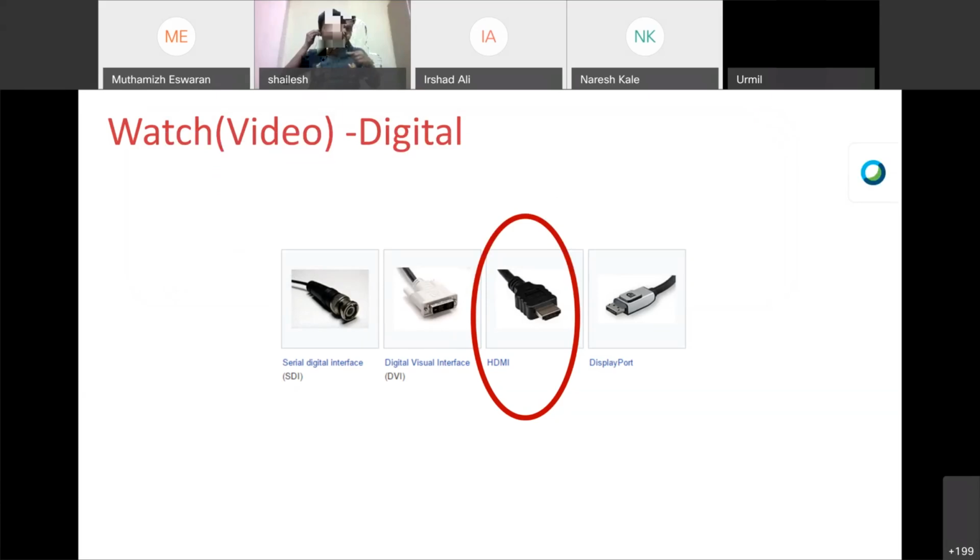Now the next thing is DVI, the Digital Visual Interface. This was the first device which helped to convert into the digital platform. Because we were talking more about S-video or component, all those things. The main reason for all those becoming obsolete is the maximum video quality they can support. Even component nowadays can support a maximum of 1080p, not more than that. You cannot go 2K or 4K as such.